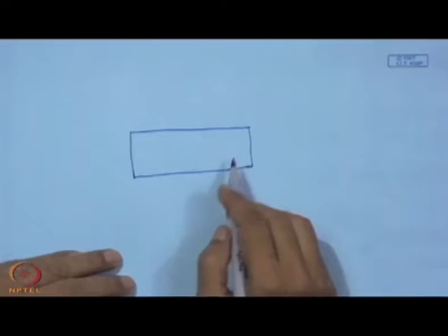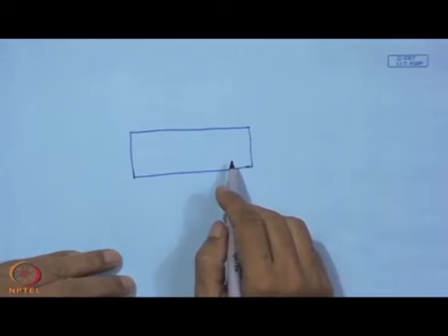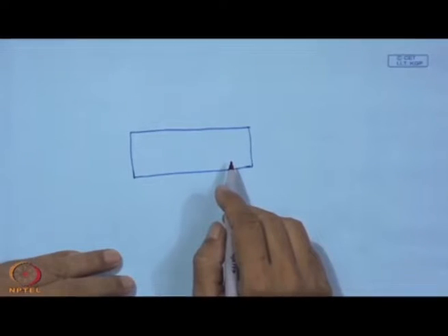Now, this surface has to be activated or passivated. We know that for diamond the surface is not ordinarily active. So, there are a lot of steps before one can start the CVD. That means substrate preparation becomes one of the important steps before conducting CVD. So, we have two choices, either activation of the surface or passivation of the surface.